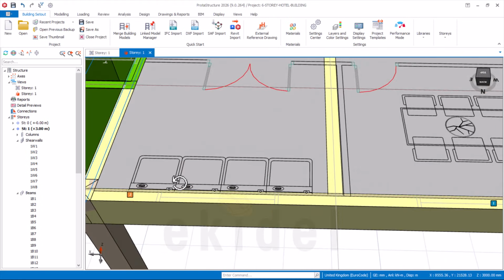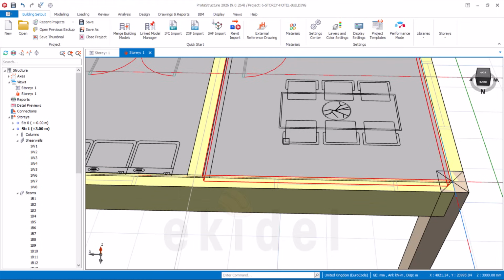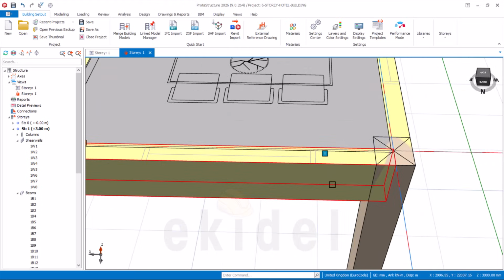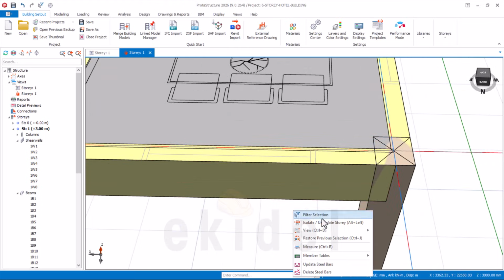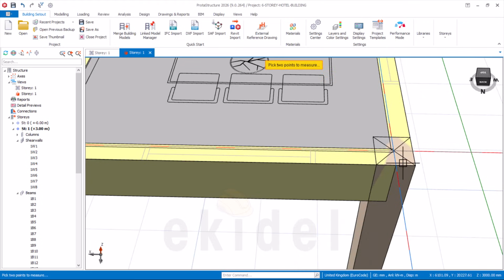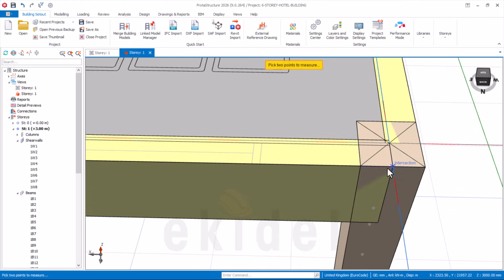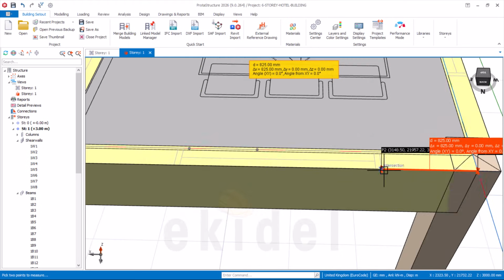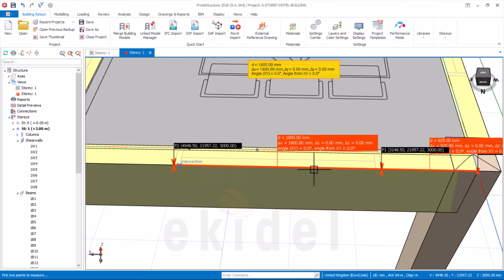Now, since we have the tracing drawing showing here, we don't need to be going to our CAD file and be doing measuring. We can just measure the distance that we need here. How do we do that? Come here right now, click on this place, right click here, and then say measure. Measure from center point here to the point of this window starting here. What do we have? We have 825, and then what is the window opening from here to here? We have 1.8.